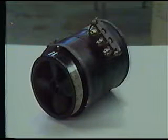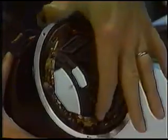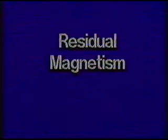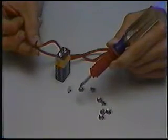This component has already been described in a previous tape. Now let's look at its internal workings in a little more detail. We will begin with what the starter generator begins with, residual magnetism. Residual magnetism is a characteristic of all electromagnets. You've probably seen someone magnetize a screwdriver by making it into an electromagnet for a short time.